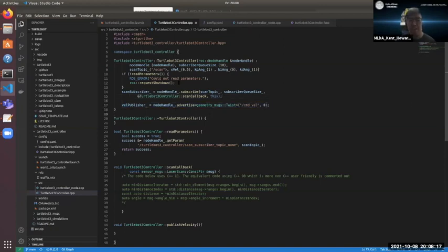So this is already explained in our last workshop. For subscribe, you put the topic, the queue size, then you put the callback function, and yeah, put this because this is for OOP. And then working with the publisher, you advertise the message type and the topic you want to put out. That's pretty much the short explanation.